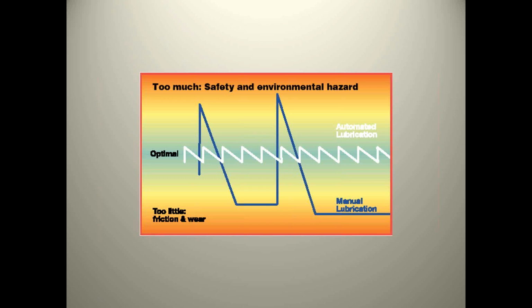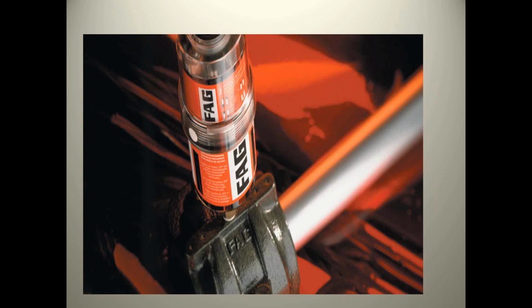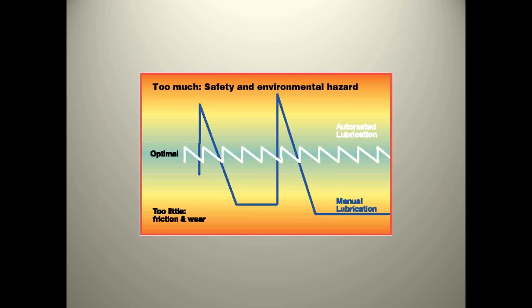So the story on this bearing back behind here that we just looked at: these bearings went from a greasing cycle of every week, putting 4 shots in, which was using a lot of grease, and those bearings lasted 8 months, to what you see here with this automatic luber on here, with this bearing now getting a film of grease on it constantly, and this bearing went to a life of over 3 years.